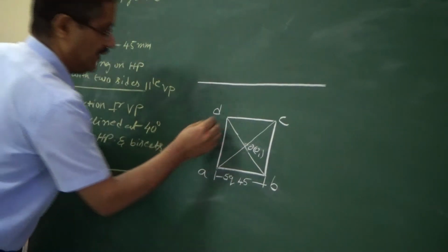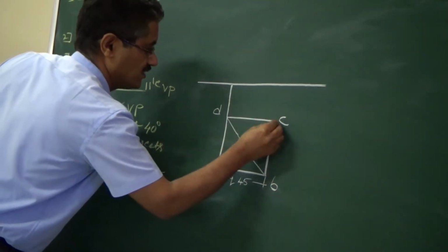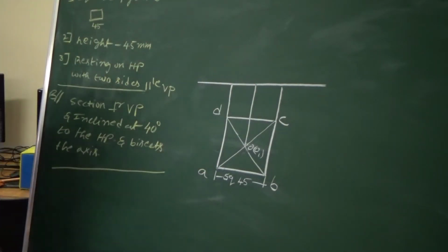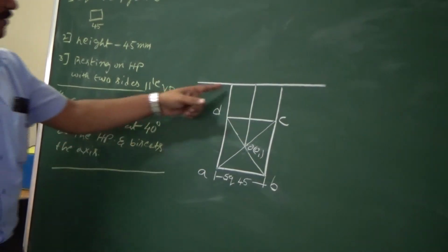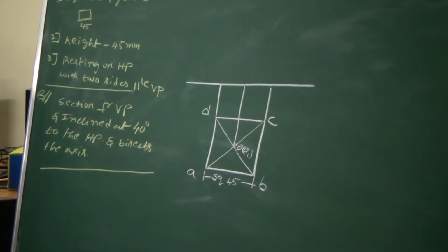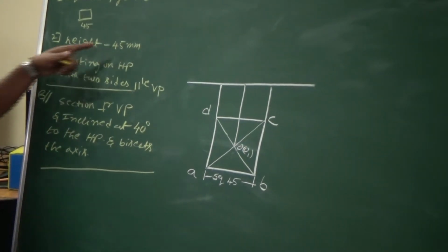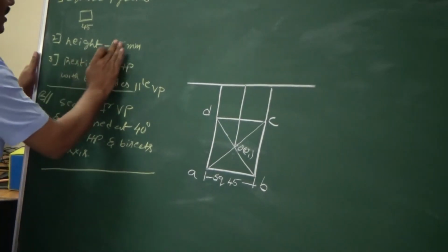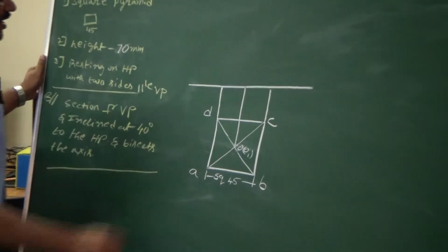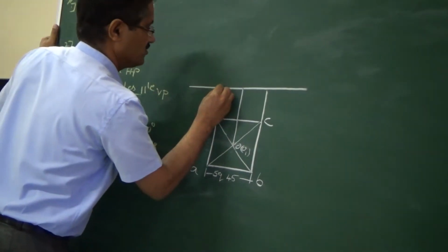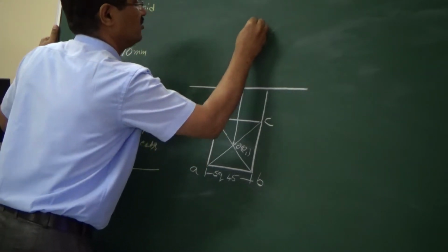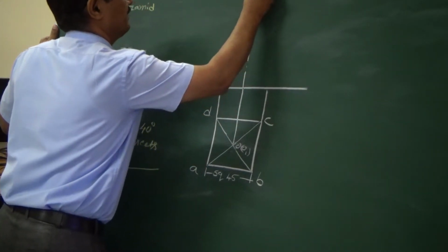Now we will take all the vertical lines from this, including the axis line, to the front. In the problem he has given the height as 45, but 45 will be very short, so I will change this height to 70. Just take the axis line to a height of 70.